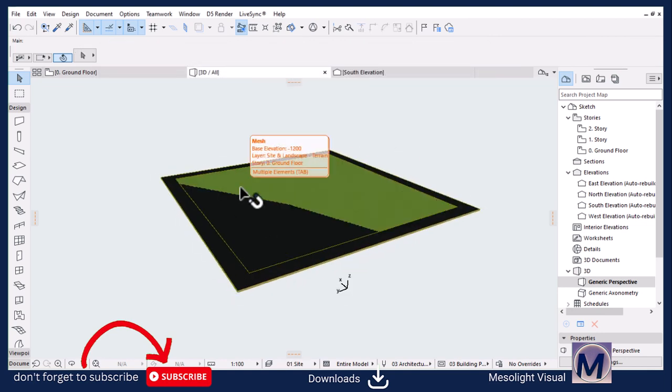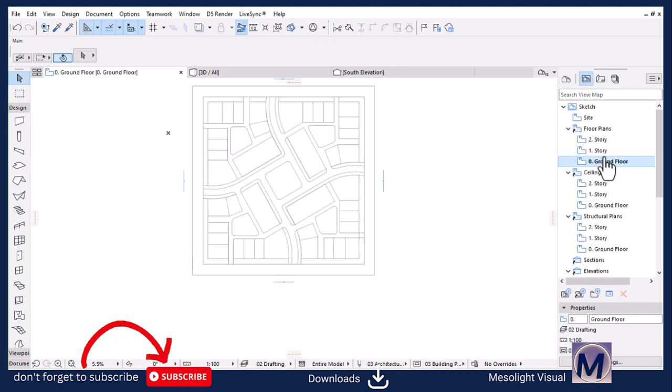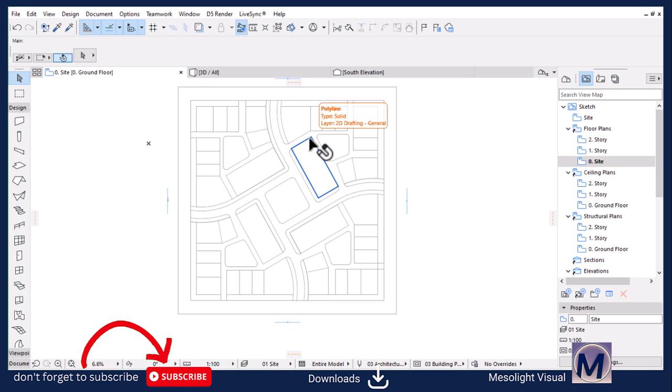So because we are working with the site combination, let's move on to the view map and then click on the ground floor plane. Let's rename this to site, because it's the only view on a level that I'm going to use, just for the sake of this demonstration. Perfect. And then if you click on the settings down below, let's set the layer combination to site, then hit OK. Perfect. So we have everything in place.